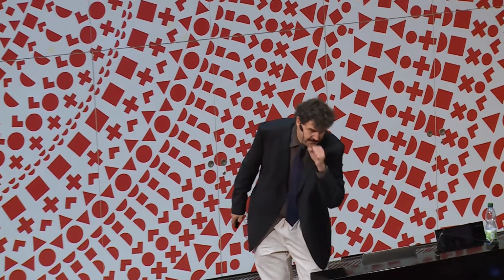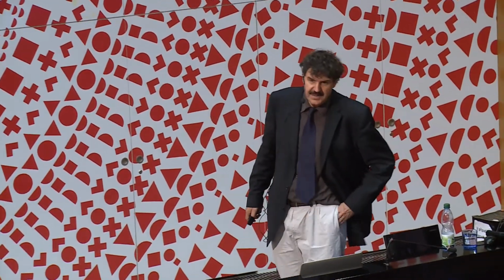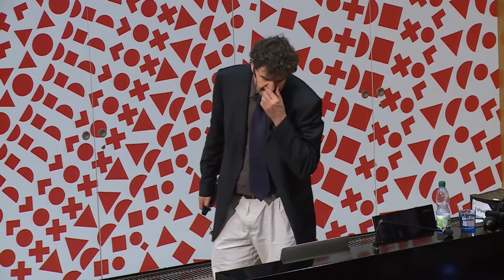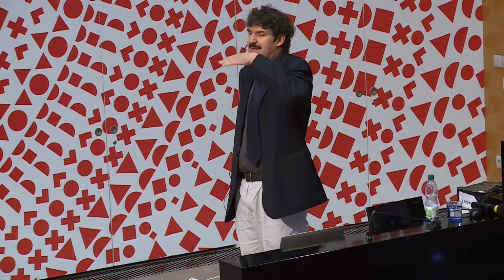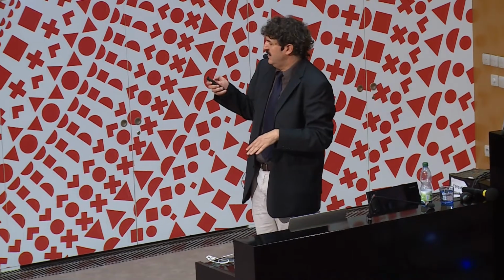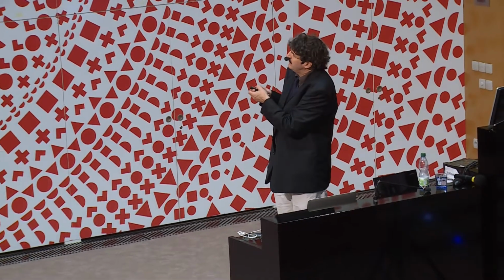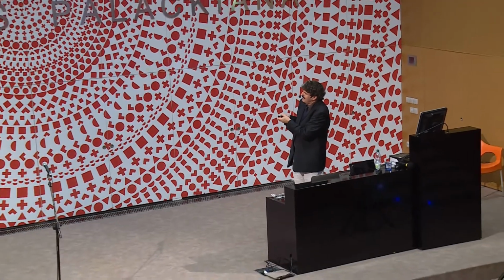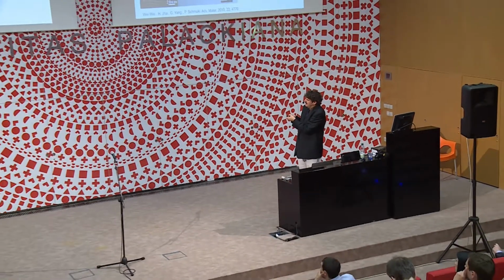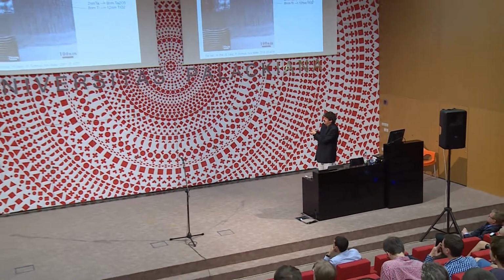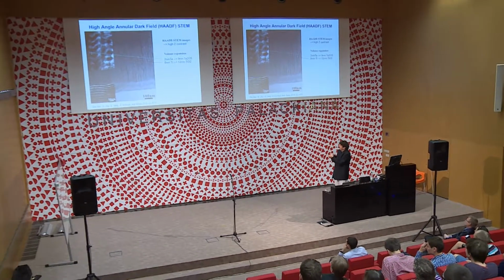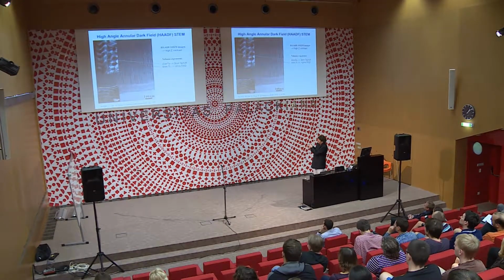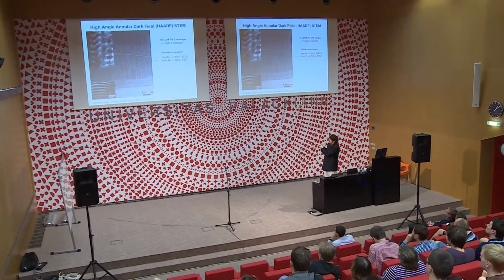Another possibility of mixing things or getting elements together is growing tubes from metal stacks. So this here is a tube layer grown on a titanium tantalum multi-metal layer stack. This metal is a sputtered layer of titanium and tantalum, and these original layers consist of 2 nanometers tantalum and 8 nanometers titanium.